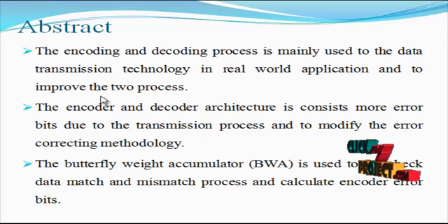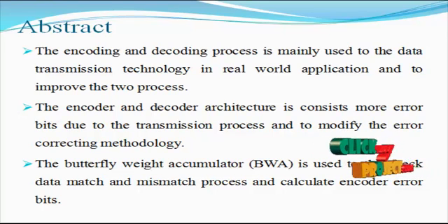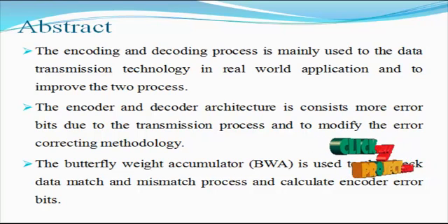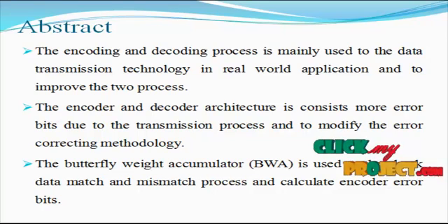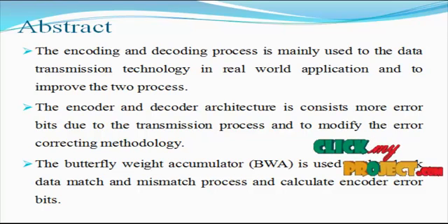Next we see the abstract for the product. Data comparison is widely used in computing systems to perform many operations, such as tag matching in a cache memory and virtual to physical address translation in a translation lookaside buffer. Because of such prevalence, it is important to implement the comparison circuit with low hardware complexity.